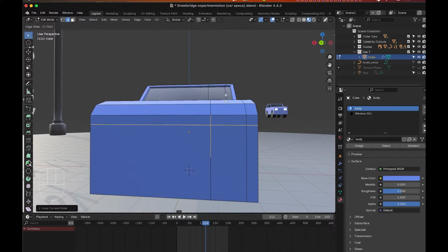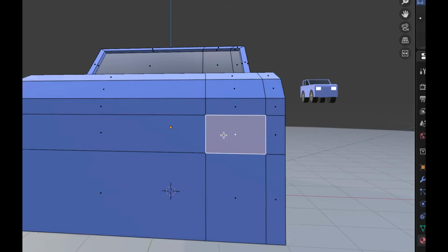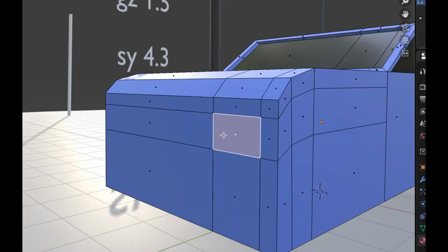I'm going to put my light here. Control R. This is up to you where you want to define it. Mine's going to be this little rectangle here. Clicking there. So now I'm pressing 3 and then clicking the area that I want to be the light. Press E to extrude inward and then move your mouse and then click.